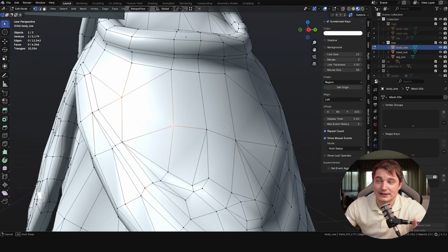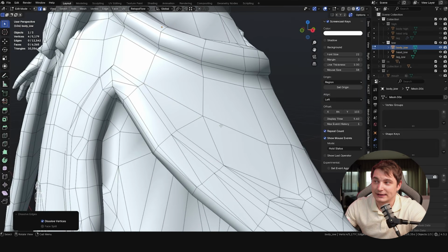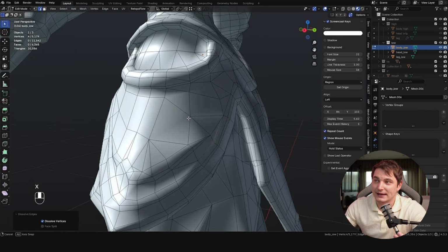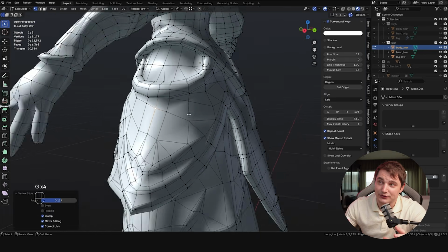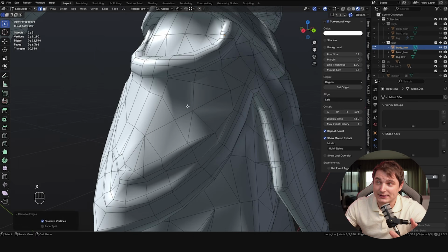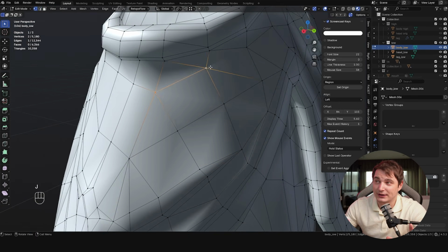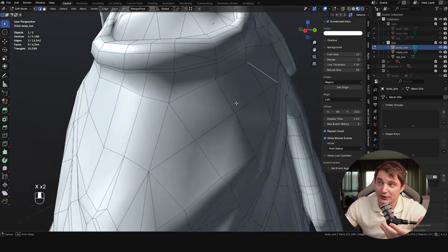You can fix most of the issues in topology. Especially, for example, here in Tripo, you can see it's quite nice and it's not that difficult to create right loops. This is, of course, about the effort. If the mesh is completely messy, maybe that doesn't make sense to do, and you regenerate or do it a different way. But in this case, you can do it like that.